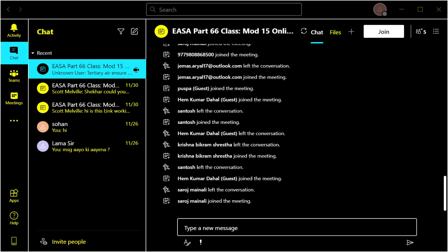And then we have what's called a last chance filter. Now, a last chance filter is a very small filter, only about that sort of size, a very, very fine mesh, and it's called the last chance because it is the last form of defense before the oil goes to the actual bearings. Now, you can only change these really when the engine goes for refurbishment or is stripped down in an engine bay. Again, you can use them for diagnostics as well.